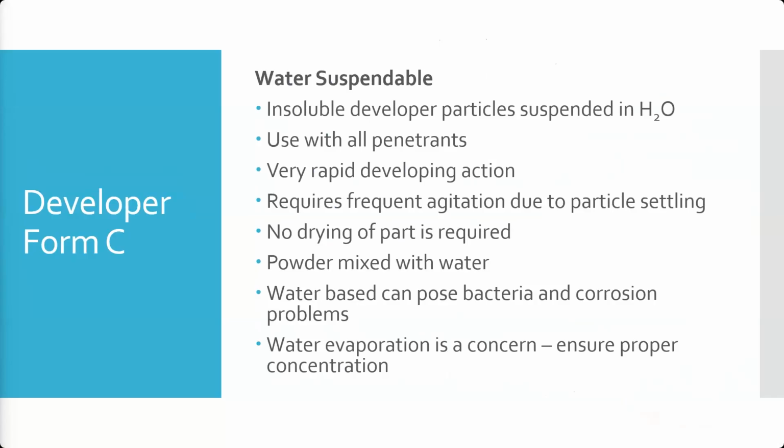Form C is water suspendable. So again, this is another powder that we mix in with water. We slosh it around with water, but here it doesn't dissolve. It is in a suspension. Being in suspension means that the particles themselves don't dissolve. They stay little particles. They're just floating around in there. So we have to keep it agitated, otherwise all the particles settle to the bottom, right? We don't want to just be applying the water to our part when we're hoping to apply the developer. So we have to make sure those particles are floating around in there when we do the application.